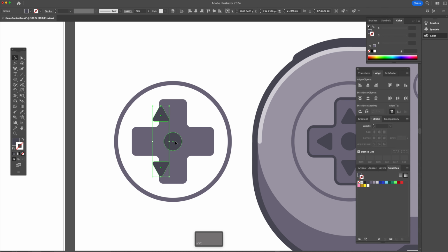So if I want to move this set of objects, this group, to have a center with my circle, once they're selected, if I click one more time without holding down any keys on my ellipse, I have now created kind of an anchoring or a key object. Now when I use my Align tool, that object is not allowed to move. It is kind of locked there.